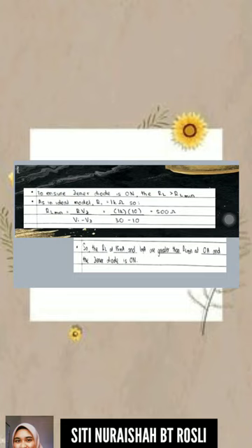So the RL at 50 milliampere, which is 2 kilo ohm, and the RL at 1 milliampere, which is 526.32 ohm, are greater than RL at 0 ampere, which is 500 ohm, and the Zener diode is on.